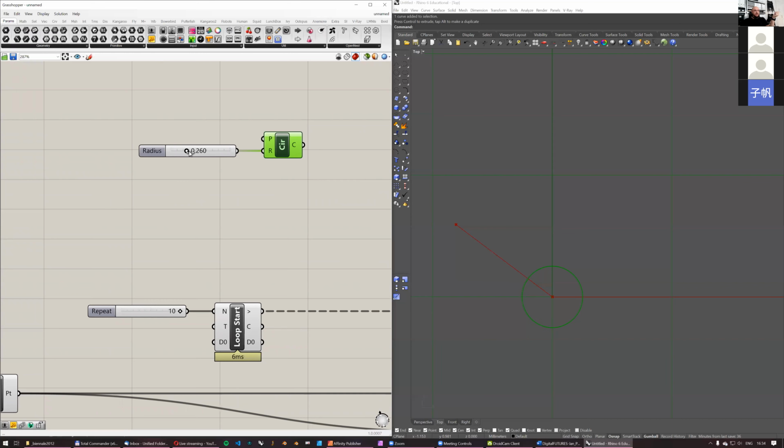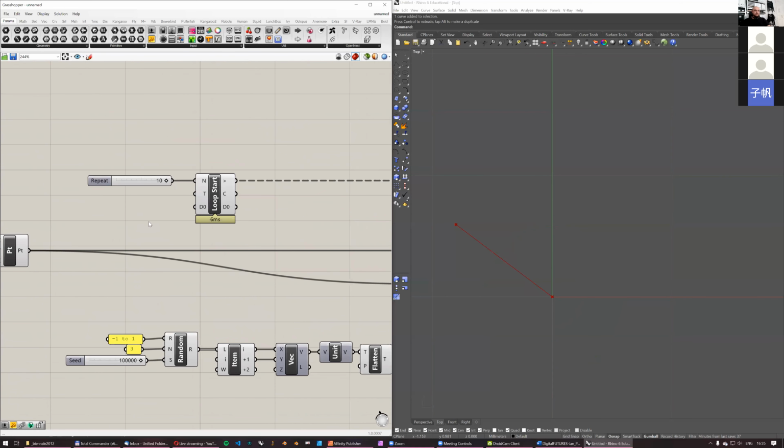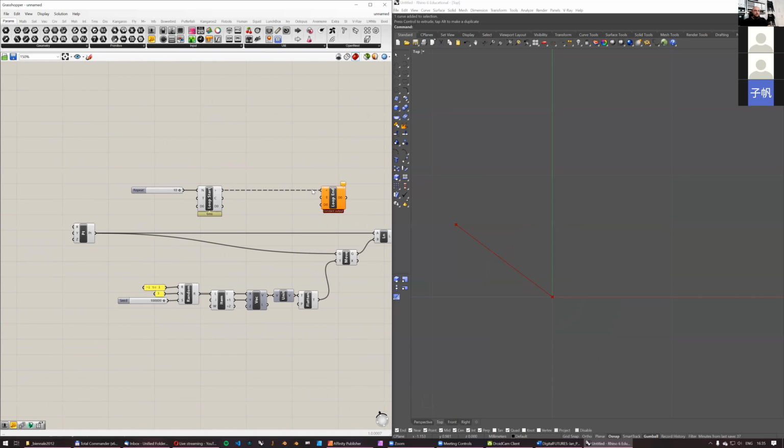But when I move the slider, it generates new data here, and it triggers this one to recompute. Because my computer is fast, and this is a super simple Grasshopper definition, this happens almost instantly. But in fact, the recalculation of this one is being triggered by the change here. Whenever I send new data here, this is being recalculated. Otherwise, it's not. The same applies here. Whenever I plug anything new here, this is going to be recalculated.